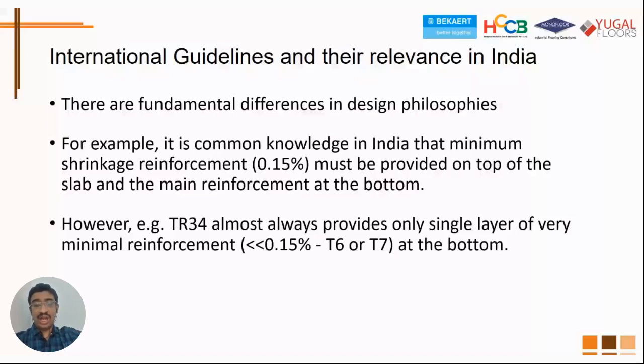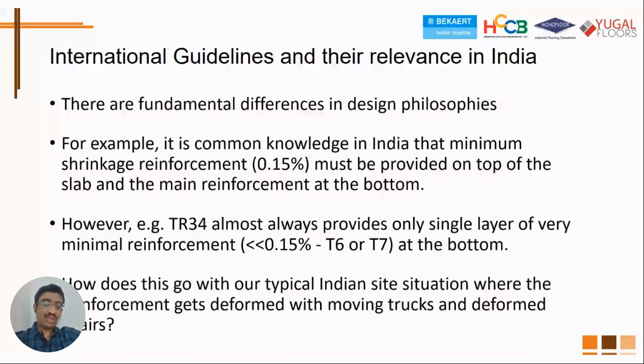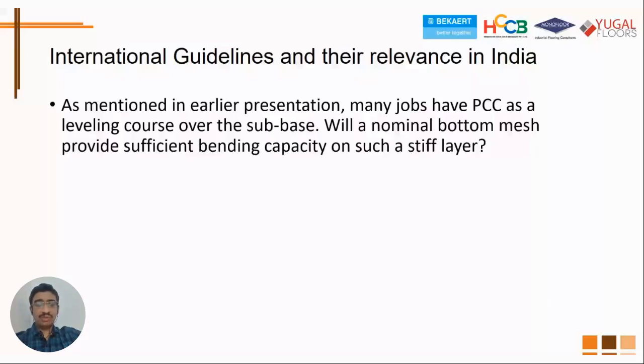And how does this go with this typical Indian situation that we have, where the reinforcements get deformed because of moving trucks, or the chairs get deformed, so the reinforcement doesn't actually stay in place. So this is an issue. And as I mentioned, Piyush has covered PCC in great detail as a leveling course for sub base. Now, if you have a nominal mesh at the bottom on such a stiff layer, do you think it's going to provide sufficient bending capacity? Now, that's also a bit of a question, if you ask me.